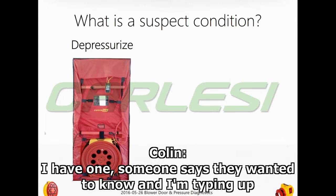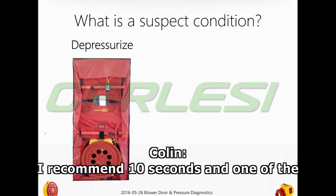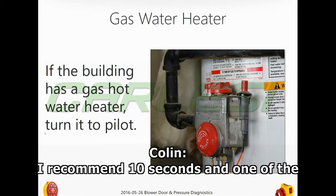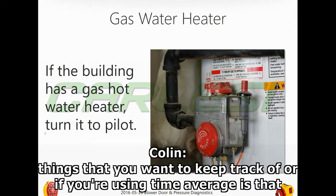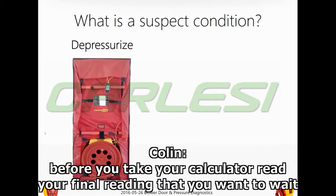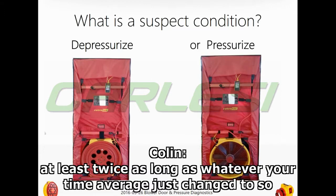Someone wanted to know, and I'm typing up the answer now, what's the most common time average reading? I recommend 10 seconds. One of the things you want to keep track of if you're using time average is that before you calculate or read your final reading, you want to wait at least twice as long as whatever your time average just changed to.